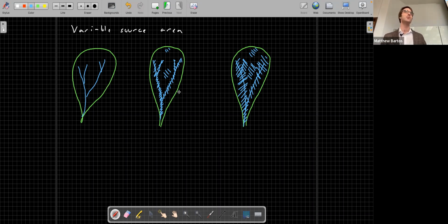I'm going to take you through the two major models that are used. There are several different infiltration models. The ones we're going to cover are the Green-Ampt model and the SCS method. The Green-Ampt model is physically based, and it will account for a lot of those parameters like saturated hydraulic conductivity, the porosity of the soil, and so on.